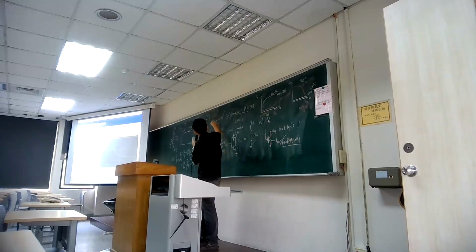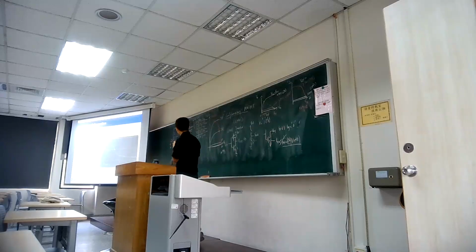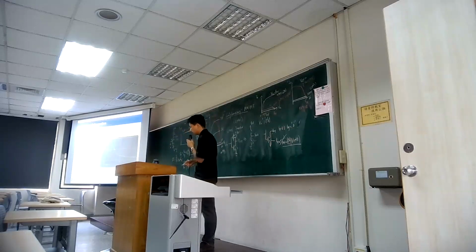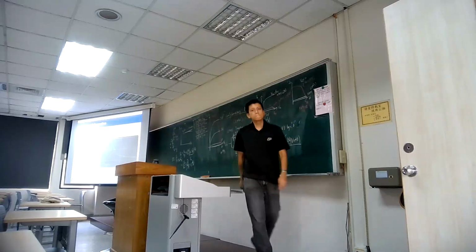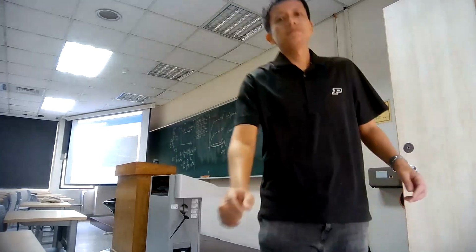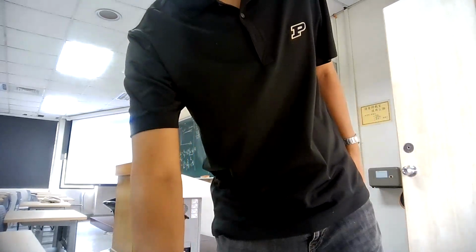You can find the crossover in the graphic solution corresponding to 0 volt to minus 5 volt. You find 0 volt in NMOS, minus 5 volt in PMOS, so you can draw the corresponding output voltage. Okay, so maybe consider this.